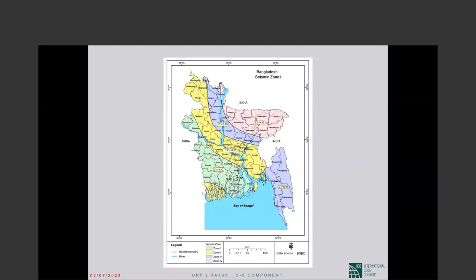It is in a different range of earthquake. So depending upon the earthquake, it now may become more critical for the building or may become less critical. You see what I'm saying? Depending upon the predominant period of the earthquake, the lengthening of the period of the building may put it in the critical range or may take it out of the critical range. So what would happen, you do not know.